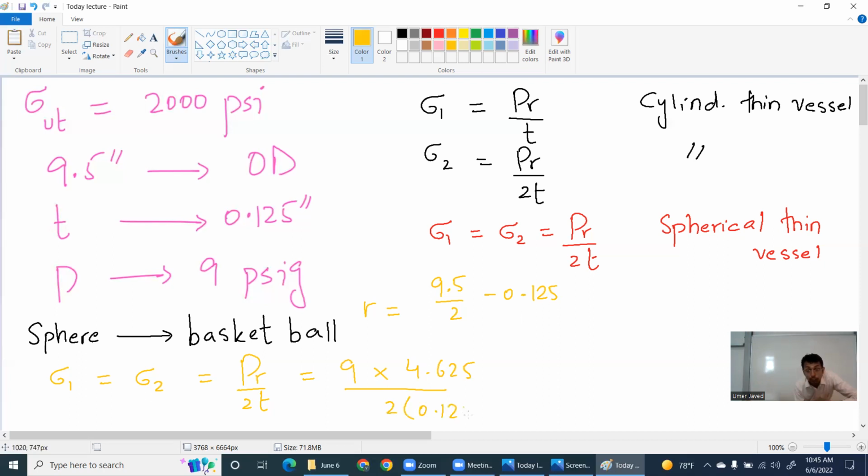Now, just for the students who have joined this class, remember that for a thin pressure vessel, there was a criterion I also told the class. R over T has to be larger than 10, where R is the, what was R? Was it inner radius? R over T has to be greater than 10 for us to qualify a cylinder as thin. So for example, how on earth would I know that a Coca-Cola can is a thin cylinder or a thick cylinder? I have to see the R. Again, I am using in this class R as the inner radius.